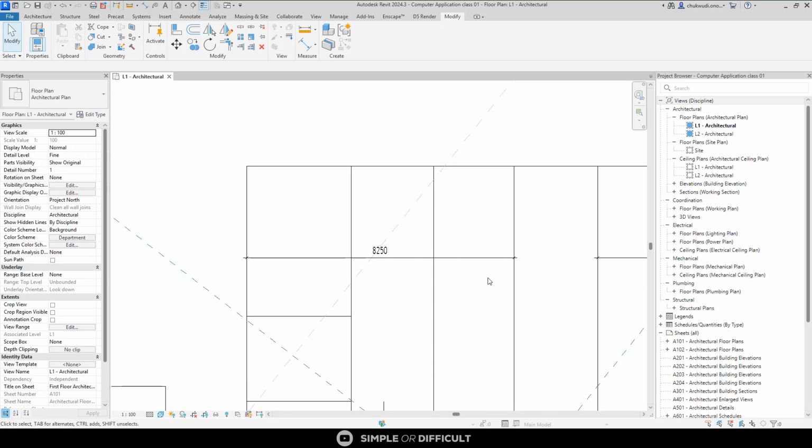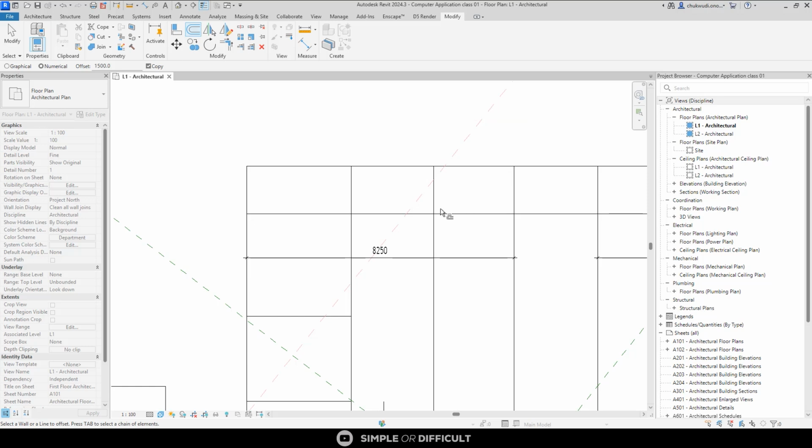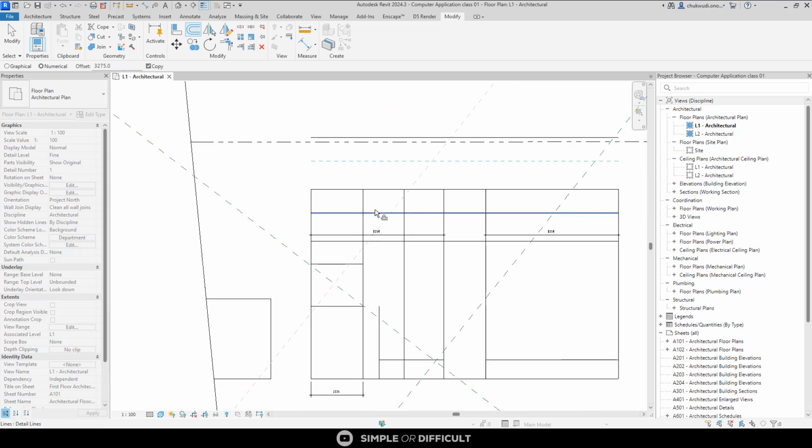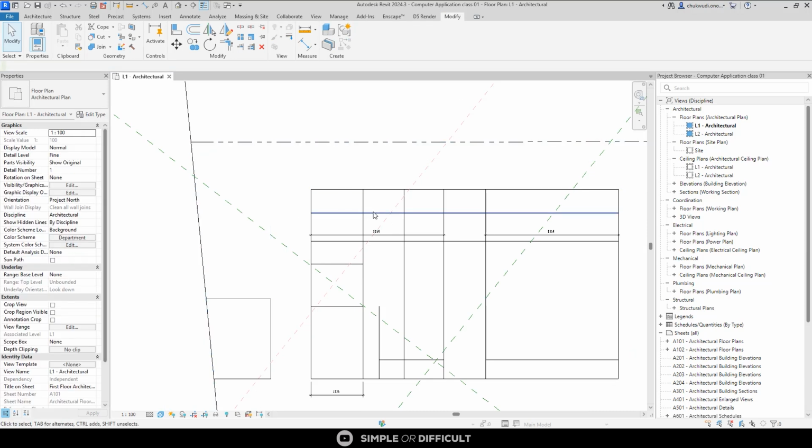Now we're going to have a dining by this side, but before that, we are going to have an entrance porch or a kitchen terrace behind there. Then we're going to have a dining. And right next to the kitchen, we're also going to have a kitchen store. So I'm going to offset 15. From there, that will be the kitchen terrace. Then from inside the kitchen, I'm going to do 3275. Offset it inwards.